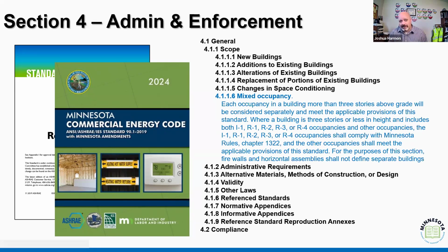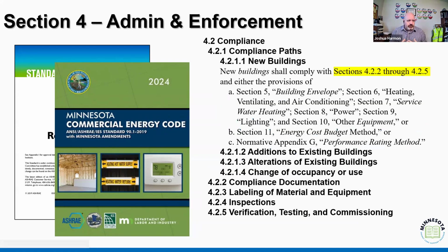And this is a 1-hour webinar. It's not. We could take hours to separate and drive into each one of these sections. But in all reality, new buildings are identified in section 4.2.1.1 to comply with one of the 3 options, right? They can comply with the prescriptive elements identified in sections 5, 6, 7, 8, 9, 10, or they can comply with section 11, which is going to be the energy costs or the normative appendix G, the performance rating system.